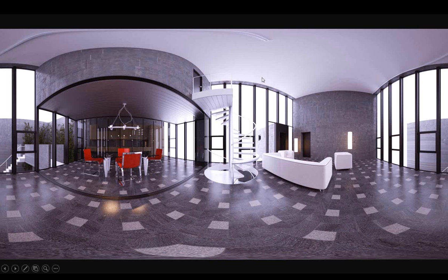Next up are the new lenses. So this is an example of a spherical lens we added. So you can now easily do 360 renders, which are useful for mainly two reasons. One reason is you could take this and use it as an HDR illumination, so that, for example, if you have a character walking around in this scene, you don't have to render the entire interior for every frame. You can just use this as an HDR environment light, thus saving you a lot of render time. And of course, also you can do walkthroughs for your website. So you can take this image and do a 360 visit of an interior or such things.